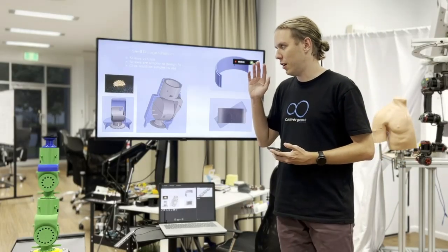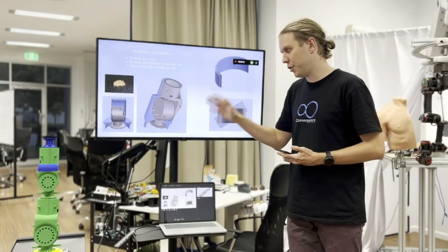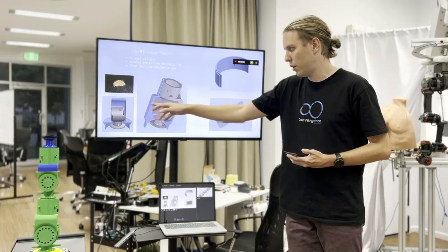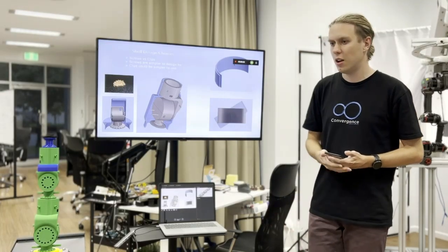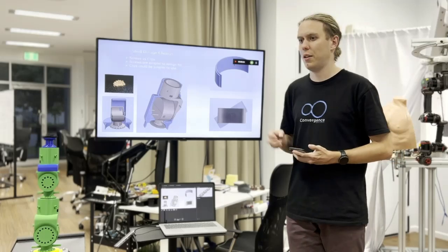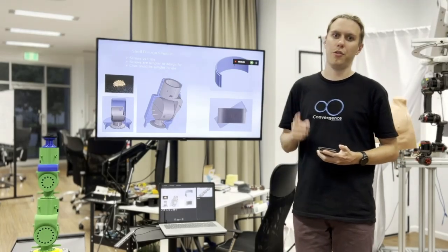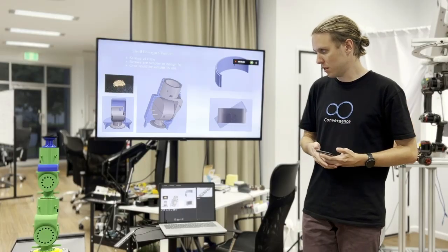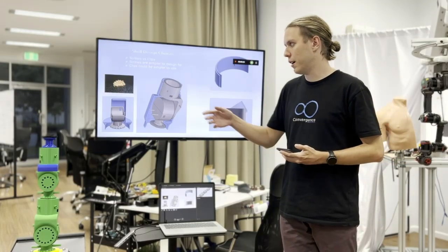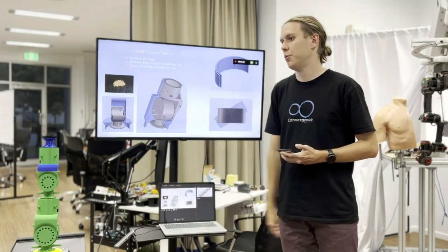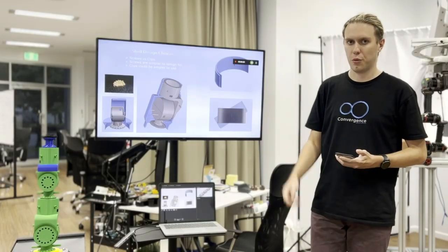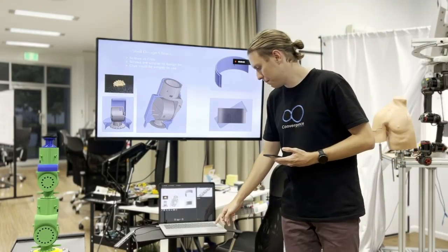So the design that I went with was to use screws. As you can see, there are bits that are protruding out and there are holes on the outside of the shell, so you could use screws to go through there. There's two ways of doing that. We can use self-tapping screws, which would actually thread the hole for me. Or I could use pre-threaded inserts, which I could insert into the holes that you can see there, and then you just screw a normal screw into that position.